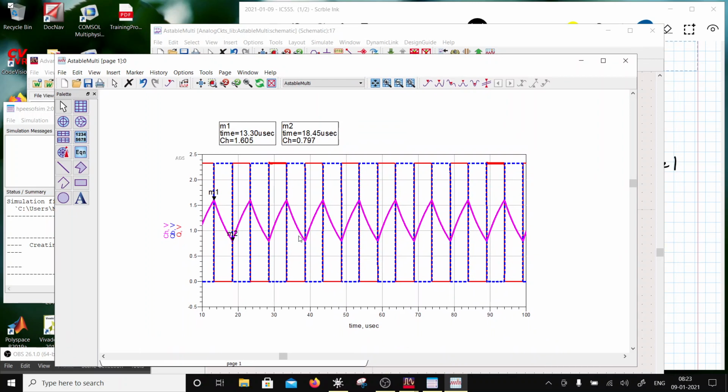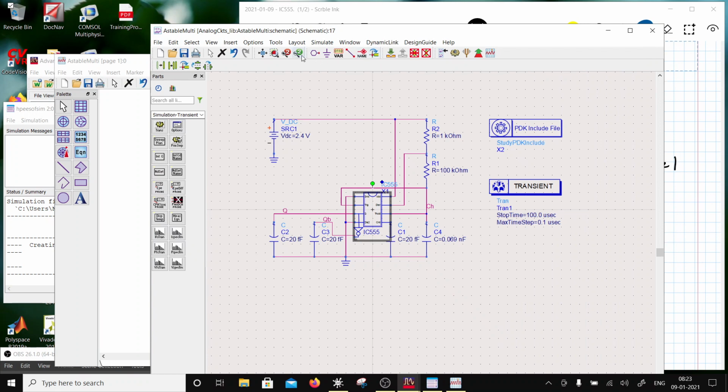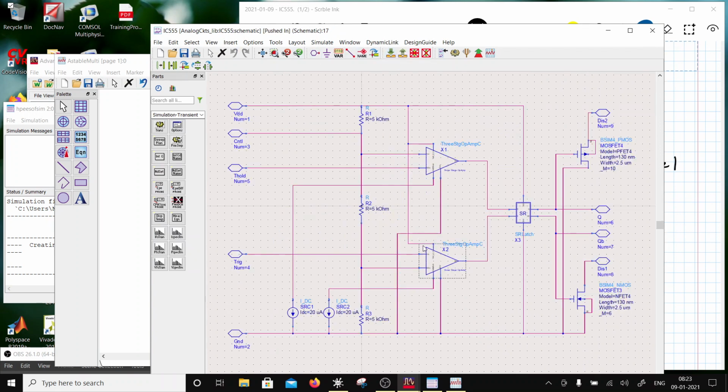So here I'm going to conclude the first application of an OpAmp. Let me go down in hierarchy. These OpAmps are operated open loop, there's no feedback, with a very high gain of around 60 dB on each OpAmp. So they are acting as comparators. Now, comparators are slightly different than just an open loop OpAmp. They have to have something called hysteresis, right? I'll talk about that when I design comparators from OpAmps.